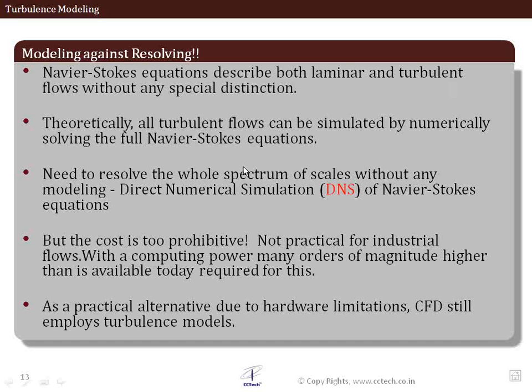The question is that such direct numerical simulation of the Navier-Stokes equations is quite prohibitive because the size of the cell has to be very small to capture the smallest eddy, and the time, because it's an unsteady phenomena, we have to march in time, we have to do an unsteady simulation, a transient simulation. The time step has to be very small so as to accommodate the behavior of the smallest eddy. So such a kind of analysis in CFD is impossible for real industrial problems, and it's not even so necessary.